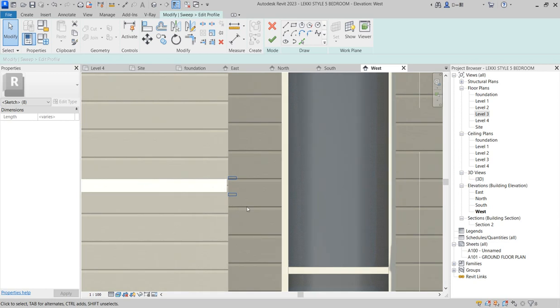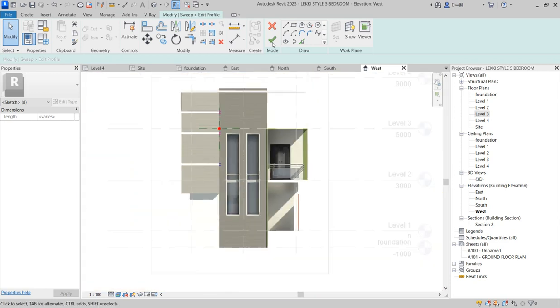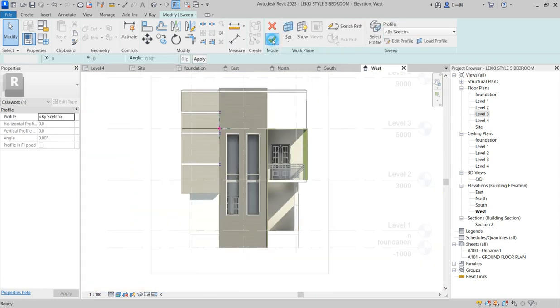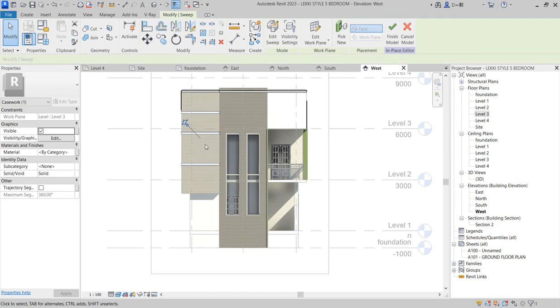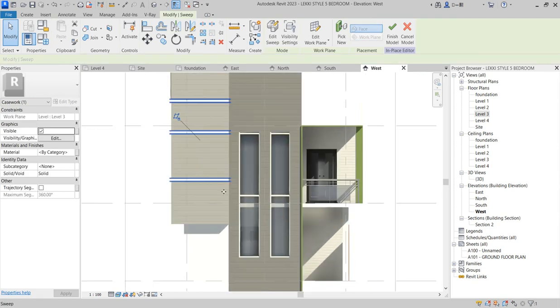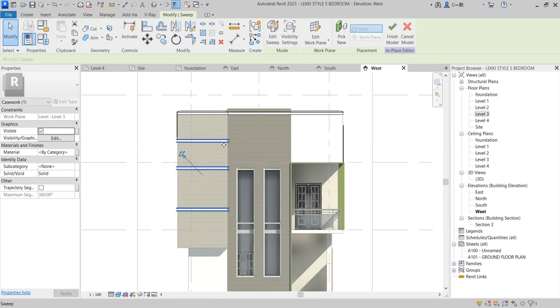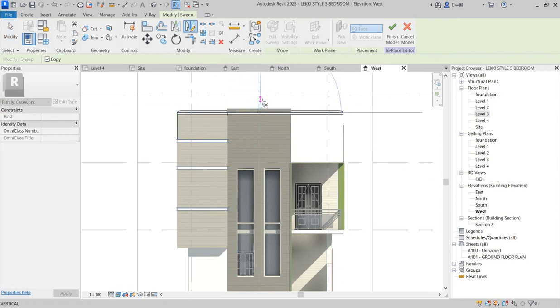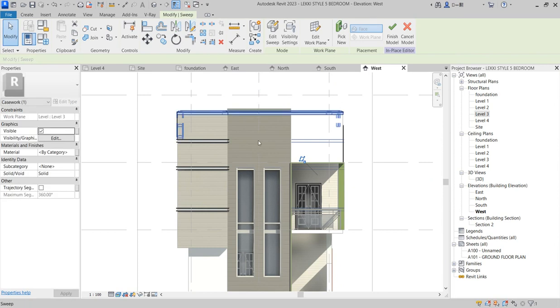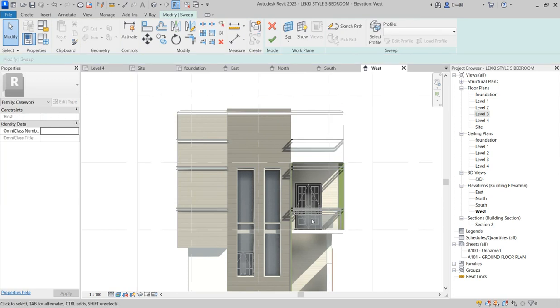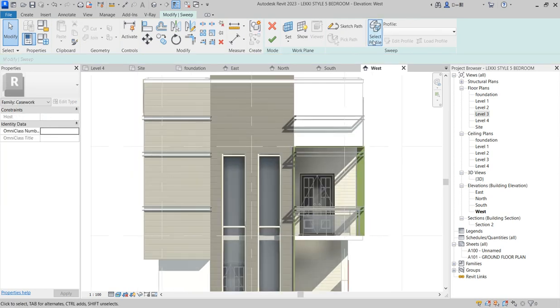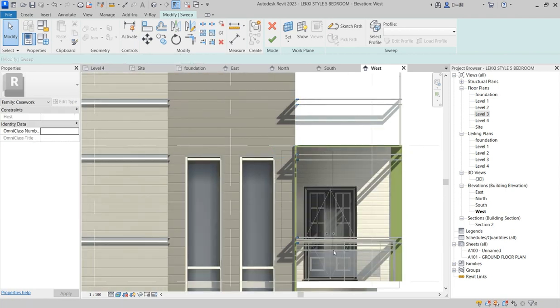So press escape. What you have done here is a simple thing. You click finish and you see the whole thing join to the left side. So you can now move this one again, don't finish it, and say mirror this the other way around. As it is the other way around now, we edit it, and what you need to do to edit is just the profile. So delete all this that is not needed.